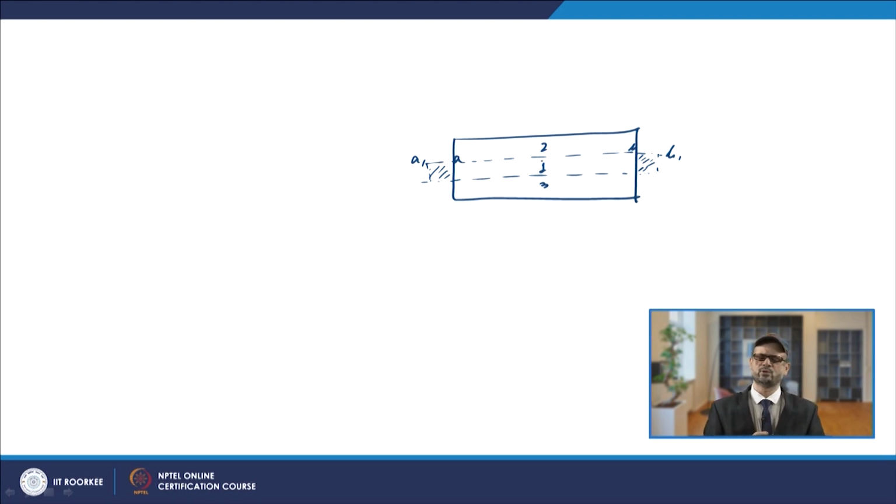That will develop the stresses on these zones. One is expanding, and the others are basically trying to stop it because they are in contact and they are not so hot. So, zone 2 and 3, since they are not hot, will be providing that restraint on zone 1. Since they are restraining it, zone 1 will be under compressive stress.